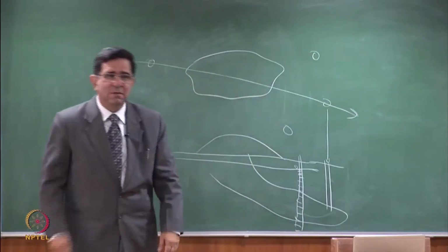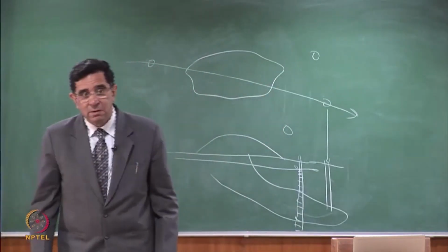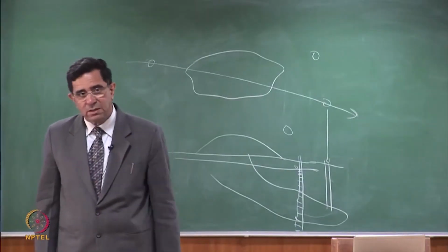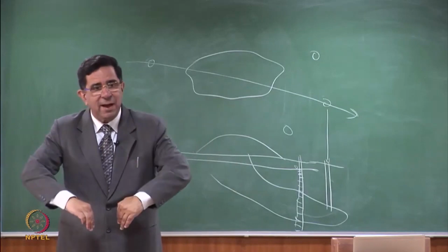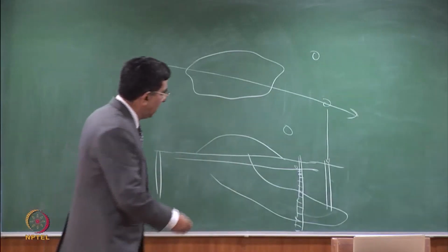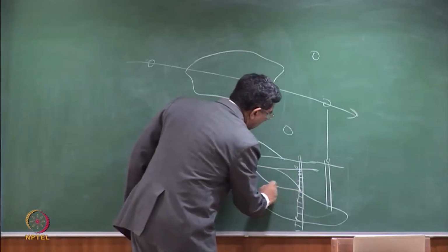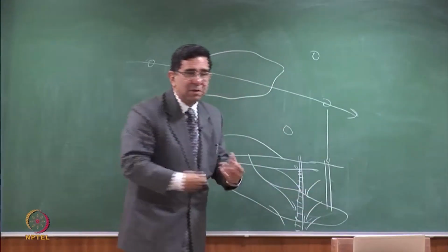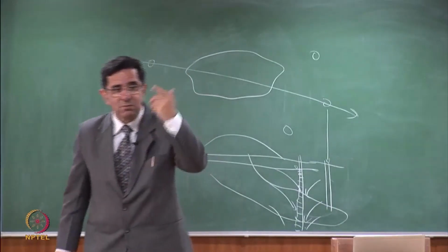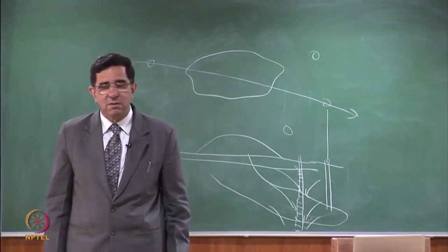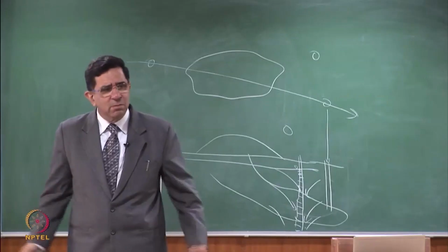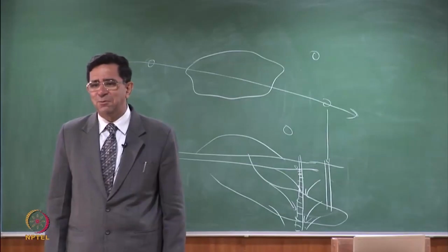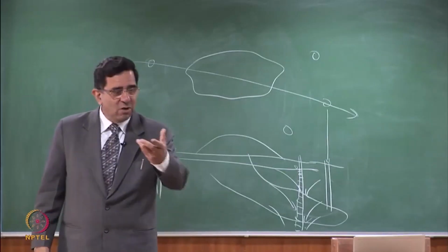I made a 20-meter long screen. How beautiful. I don't know from where the contamination is coming. Why? When I suck out the water, it is falling through the gravel pack. When I take the sample, the water is falling through the gravel pack. This is coming as a mixed sample. So I'll say, okay, from what depth is the contamination? Sir, it can be between 5 meters to 25 meters below because my well is collecting the sample from 20 meters.